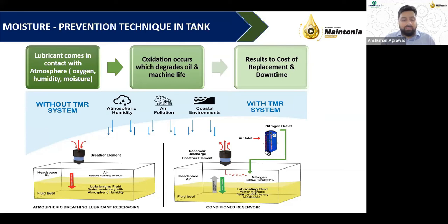Now, all this water vapor, which is present in the environment in the form of humidity, comfortably enters the tank headspace through various sources. These sources might be man-made or maintenance professional made, and these sources might be OEM made. But let us not debate what these sources are. Let us understand that there is humidity inside the tank. If someone does not believe it, just take a probe, insert it into the tank, and I'm sure you would find a value between 70 to 80% of humidity inside the headspace of your tank.